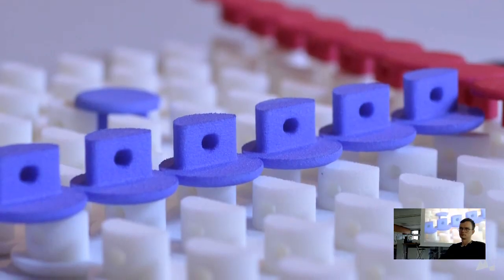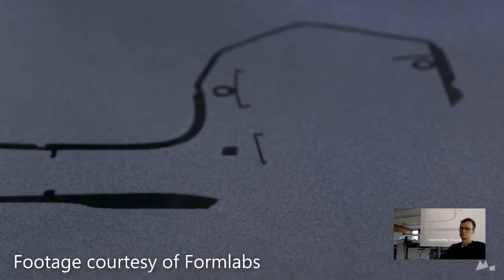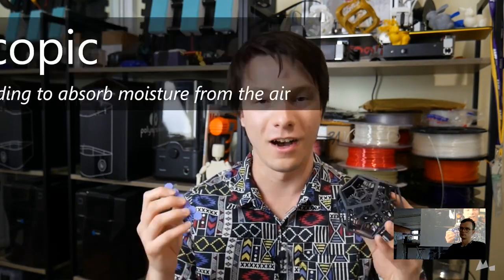Another aspect of SLS printing is this. You can actually dye it. Nylon takes dyes really readily. These are industrially dyed through Shapeways. They look fantastic, but you can actually get stuff dyed using RIT dye. And a lot of artists actually take the very nice pure white powder from the EOS system and dye it, like with tie-dye, to create necklaces and all sorts of things. These lower-cost systems are black, so you can't dye them. Again, I believe they're black because you need to use a less powerful laser source to sinter it at a given temperature, but it doesn't stop the fact that nylon is hygroscopic.